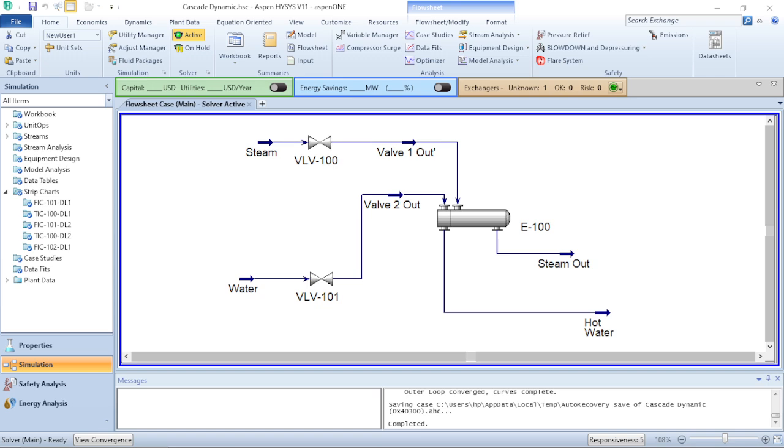So basically what we are trying to achieve here in the Cascade controller is to make the set point of the primary controller, right? The set point might be for the temperature, it might be for the flow rate, any of them. We make the set point of one controller serve as the set point for another controller, like the secondary controller.